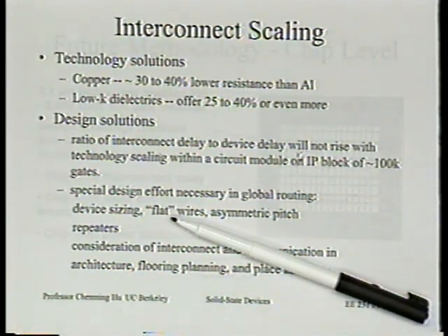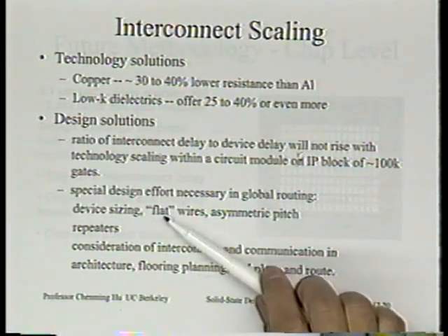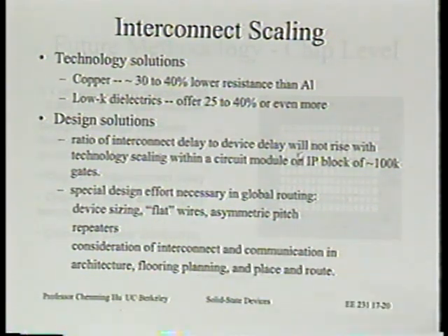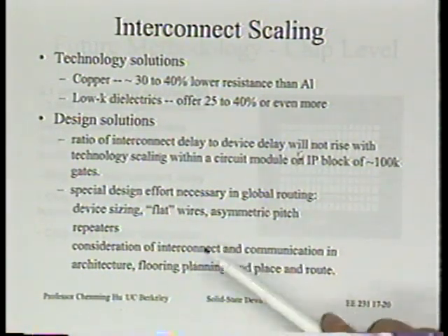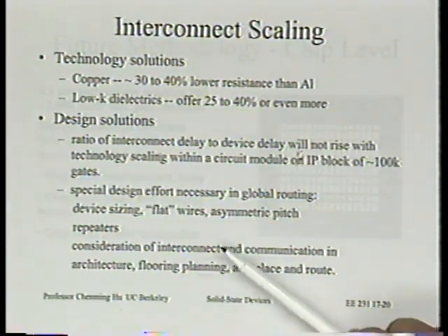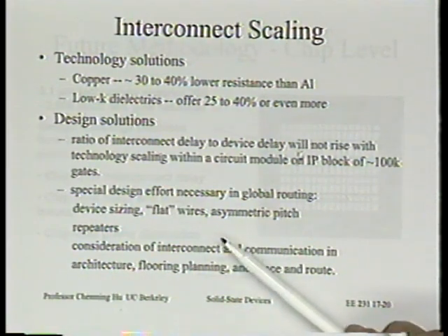By using wide wire for low resistance, I can use thinner or flatter wire to minimize the capacitance with the neighbor. You see? So that requires a detailed knowledge. How important is the capacitance relative to resistance? I may decide to do this, right? And that hasn't been discussed much, but this is one conclusion that we came up with. In some cases, this actually may be better.